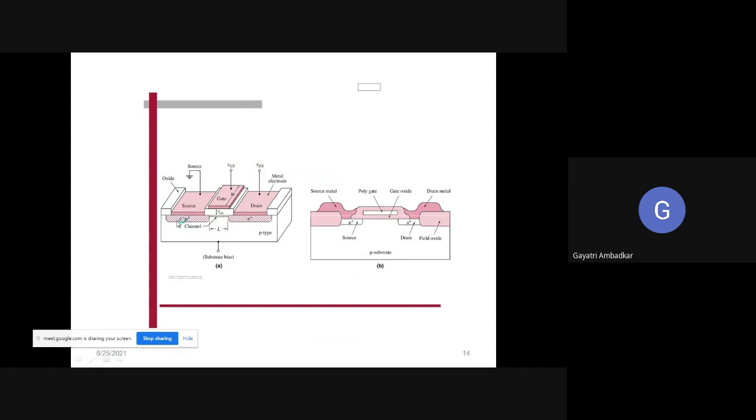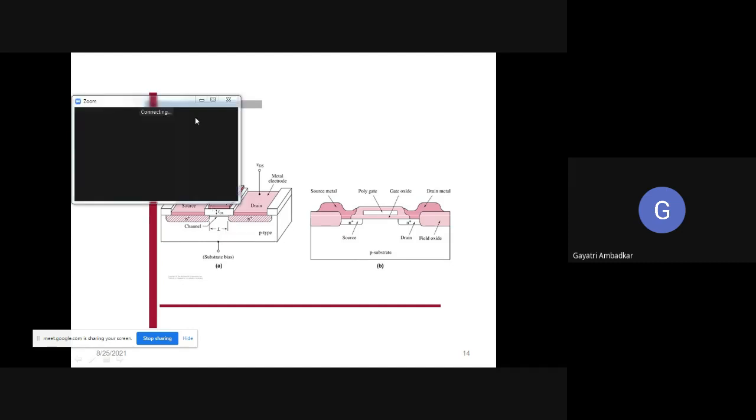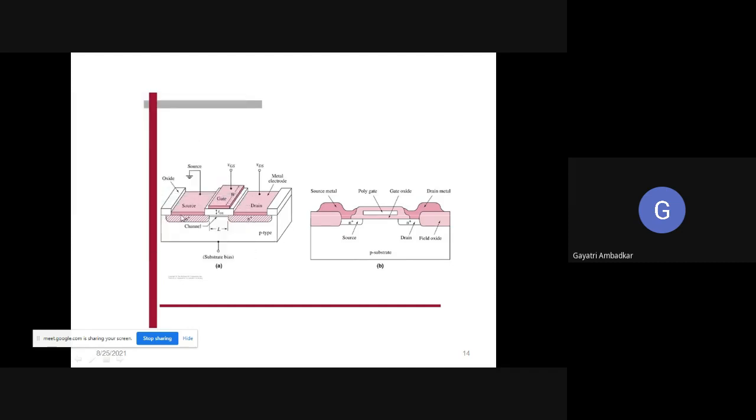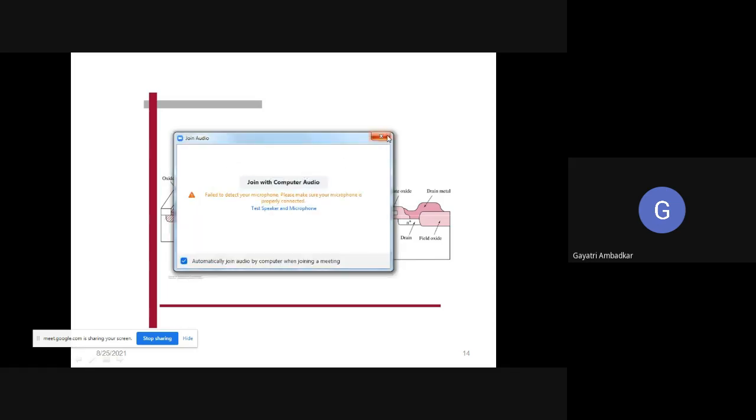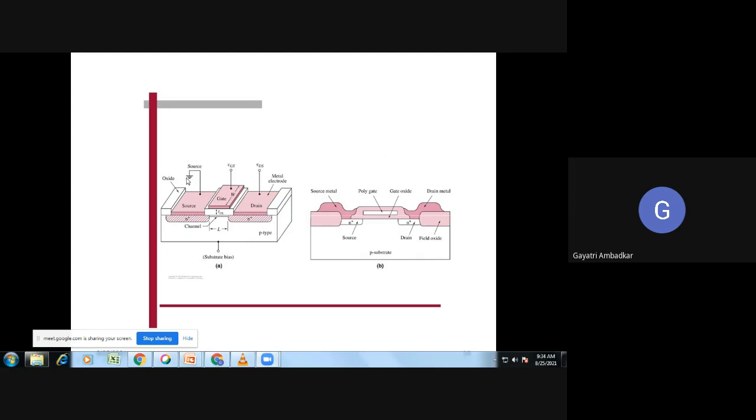the metallic contact. So see, if you cut this MOSFET, you will find the metal deposited over this N region. So inside there is an N region. This is the width and this is the length of this MOSFET. Wherever there is an N region, above that N region metal is deposited and it becomes the source. Similarly here, above the drain, metal is deposited to form a contact and it is your drain.